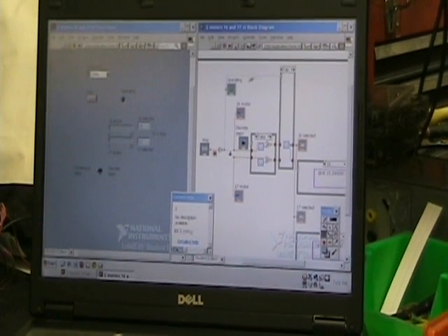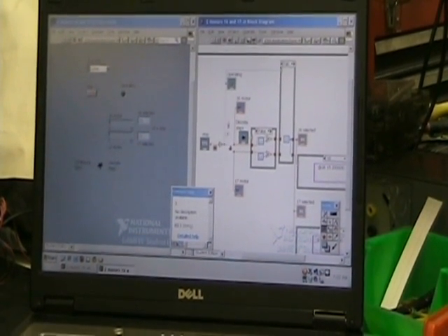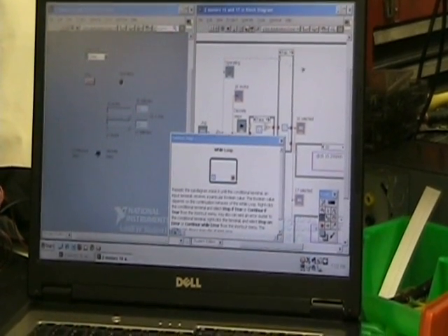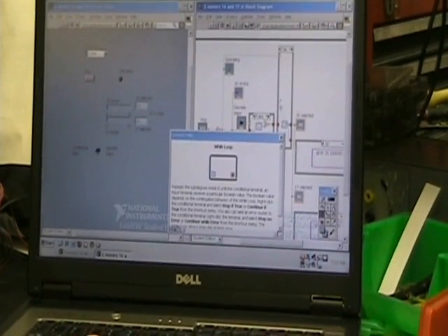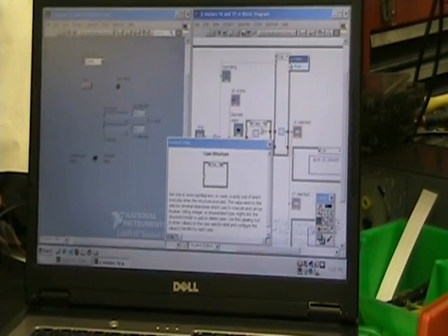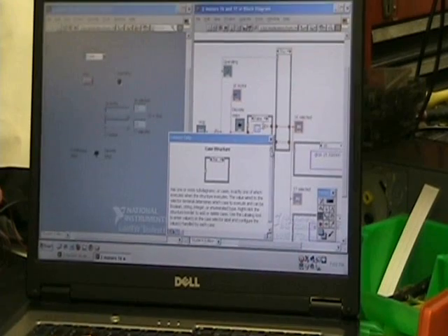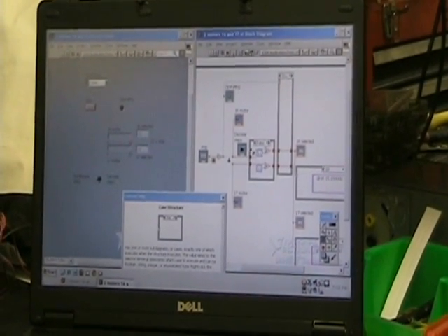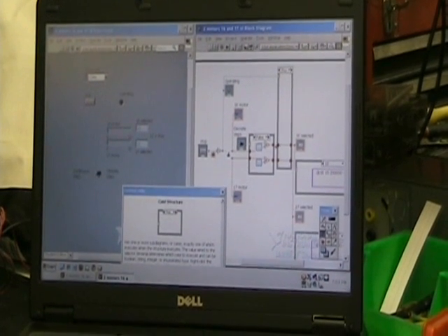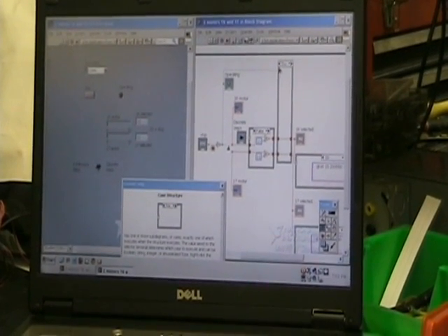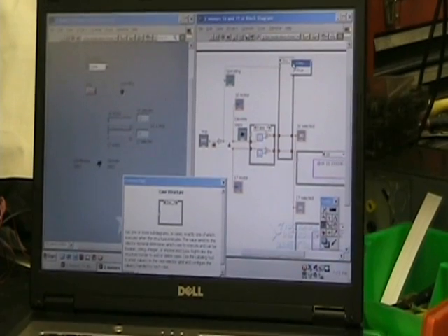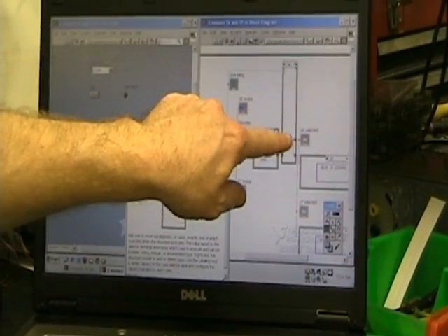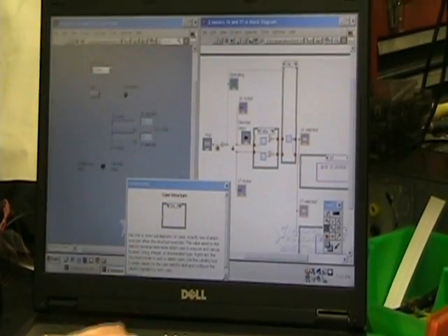One other little trick is the stop command. I'm not sure I talked about this already or not. The stop command also comes into a case structure that most of the time, if it's true, it just wires the selection made by the joystick across. But if it's false, it replaces the joystick's output with a 22, which is that instantaneous stop, tells the motors to stop instantly.